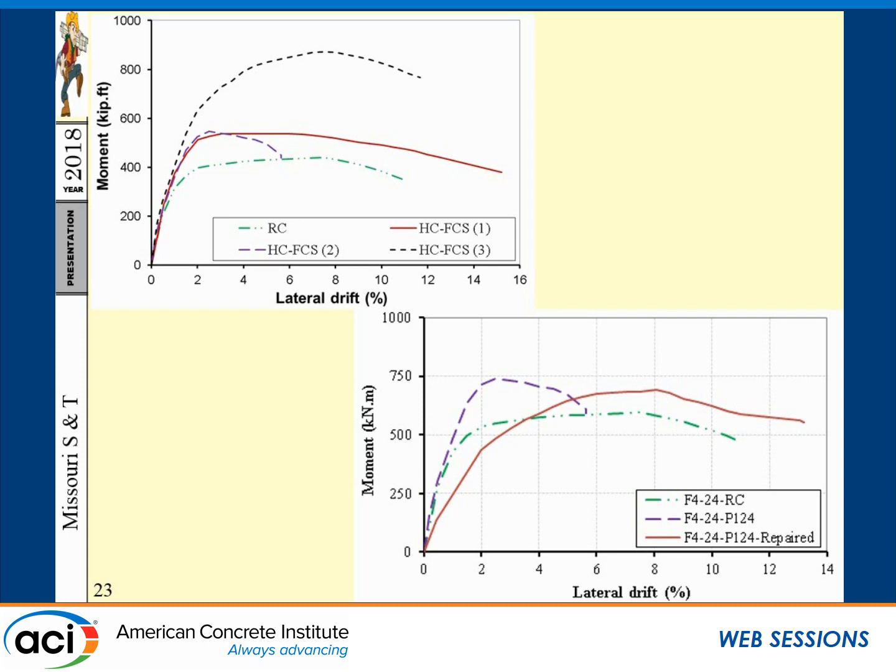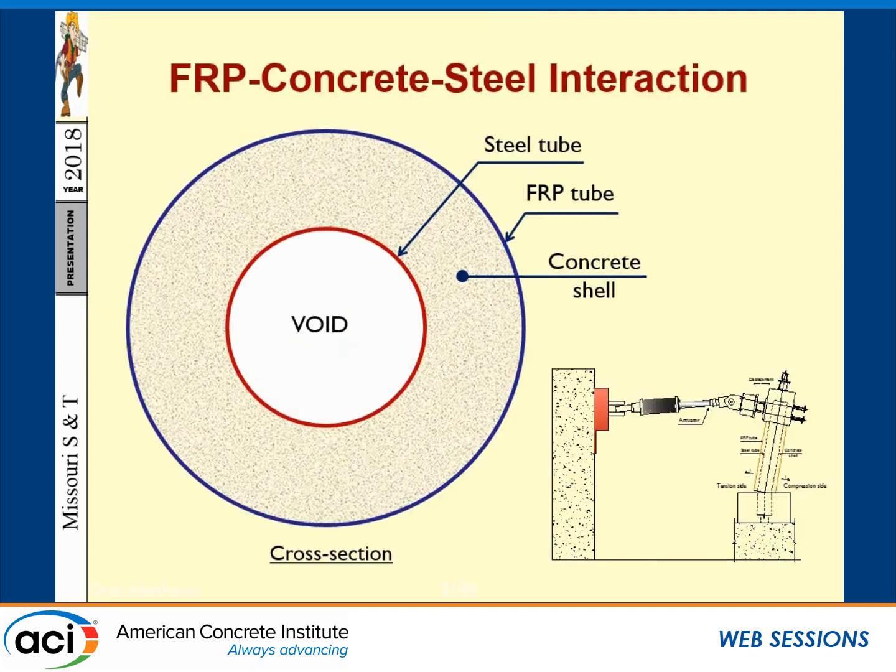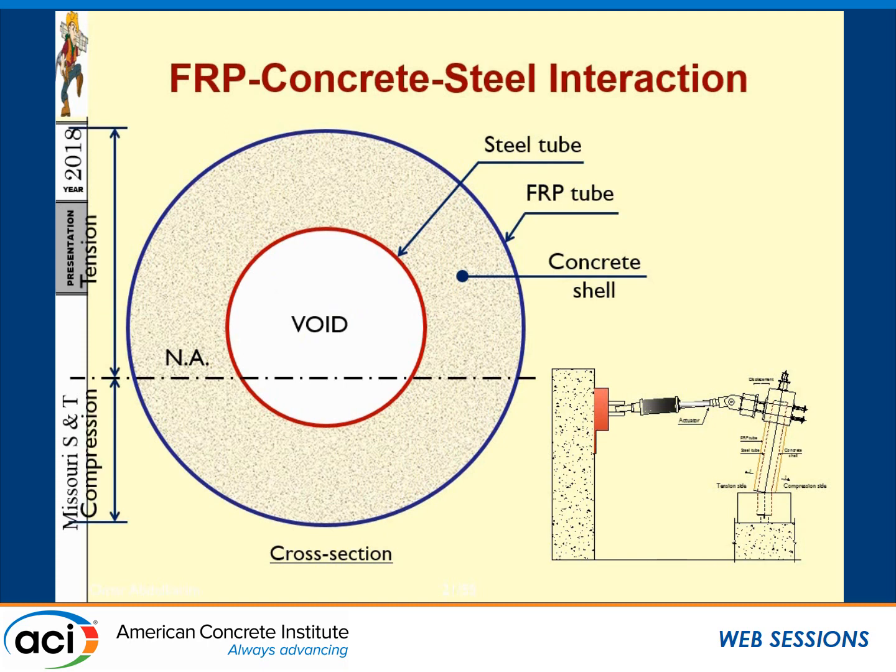In terms of initial stiffness, we cannot restore 100% of the initial stiffness. Again, in our system we did not touch the steel, which already has some residual stresses, and this is why. Plus, you also probably have some micro cracks in the concrete. And then we ended up also preparing simple calculations, or Excel sheet calculations, for the DOT.